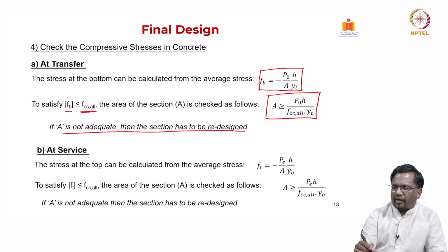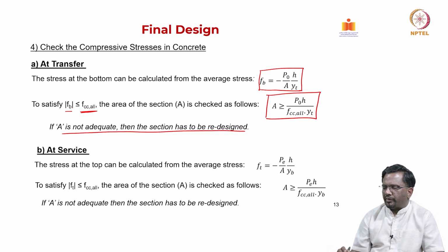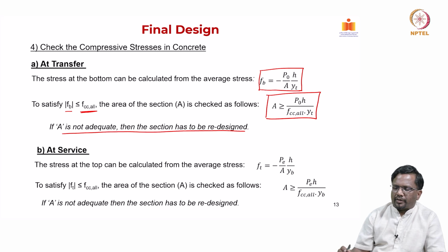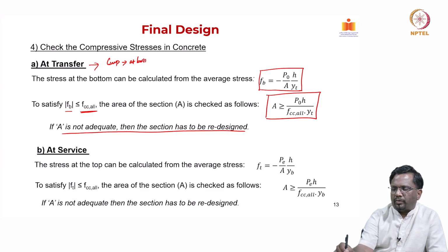Now, again, at transfer, if you look at it here, compression will be at the bottom. At service, compression will be there at the top, right.